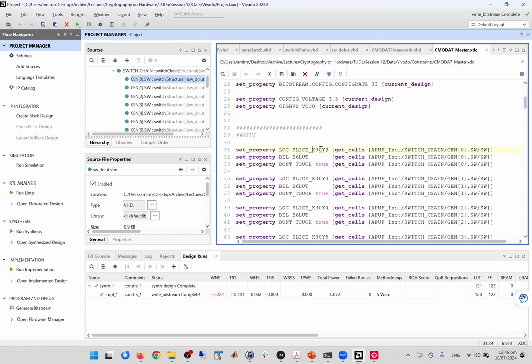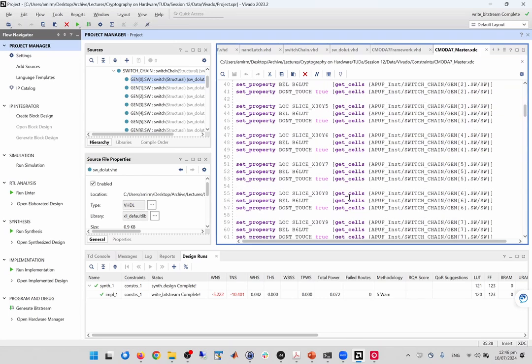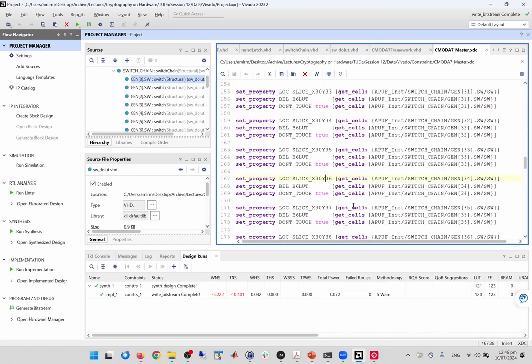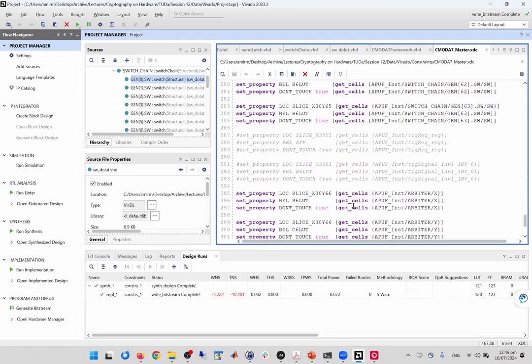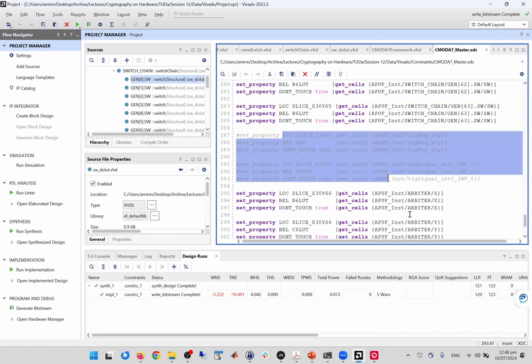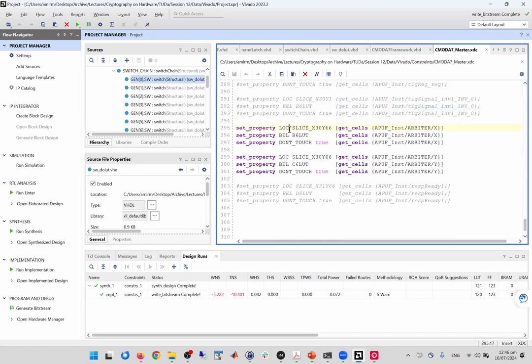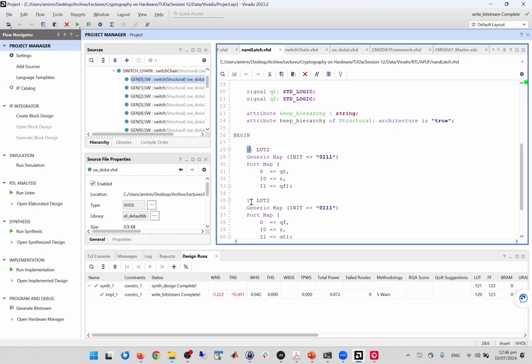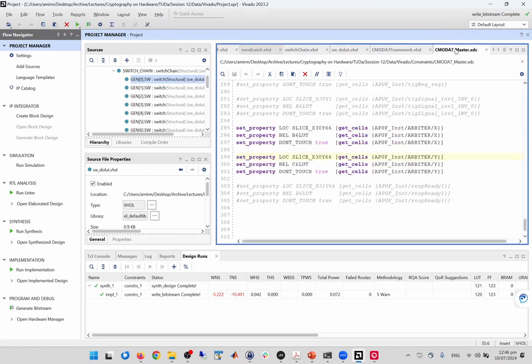Then, of course, you need to write this down by some program. You see here X30 Y2, and then X30 Y3, which means that in the same line, I will show you now, they are implemented, up to Y36, here Y65. Some of them are just comments, you should ignore them. And you can also place the arbiter. You see here I instantiated the x and y, these 2 LUTs, and they should also be don't touch so they are not optimized.